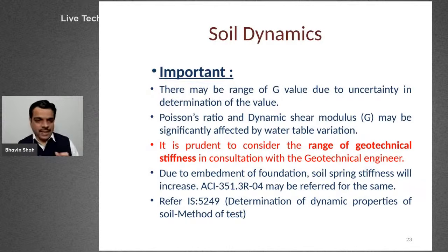we will consider this range of stiffness, because it may happen that in a certain value of the soil spring values we may be getting too close to the operating frequency. Then that is the most critical condition for us. So that critical condition needs to be evaluated, and then it needs to be further investigated for the free and the forced vibration. So that we will talk in subsequent slides. So in short, it is prudent to consider the range of geotechnical stiffness instead of considering just a single value.